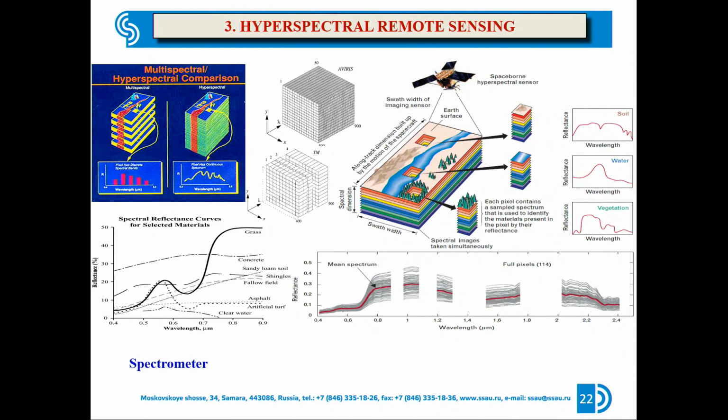Here you can understand, if we are using only 7 or 8 bands in sensors, we can only distinguish things like forest, agriculture or water. But if we are using a large number of bands, like 200 bands with narrow bandwidth, they will produce a continuous spectrum. So we will get all the information. With multispectral, we can find only one graph, but with 200 bands, each with a very narrow bandwidth, they are very sensitive to each object. So we can find out what type of soil is here, what type of minerals is here, and collect maximum information about what is on the ground.